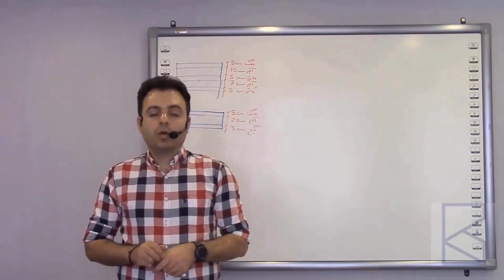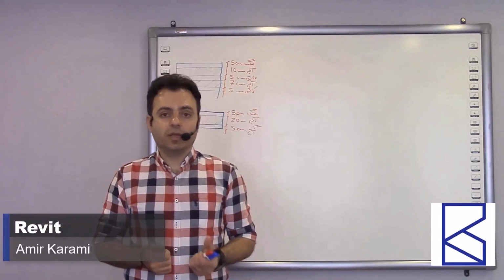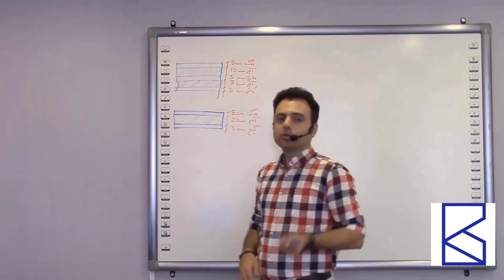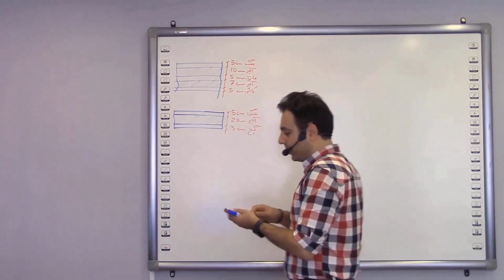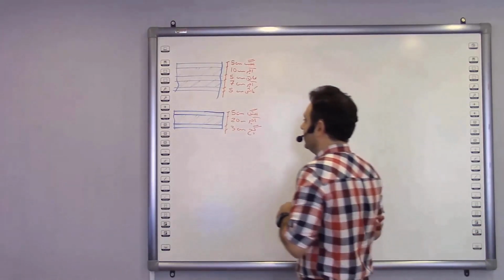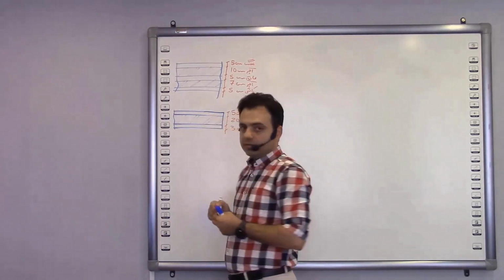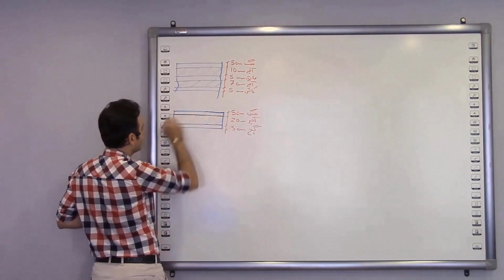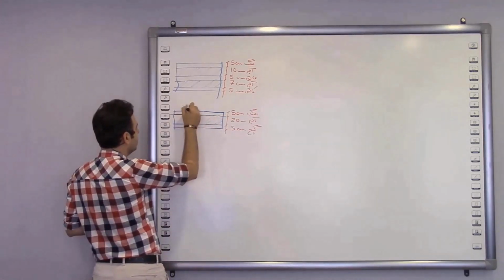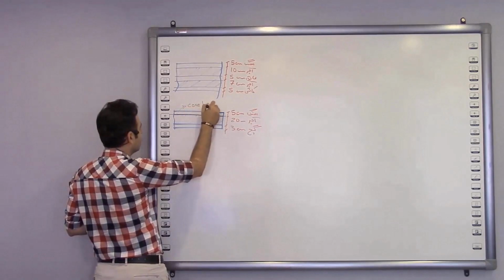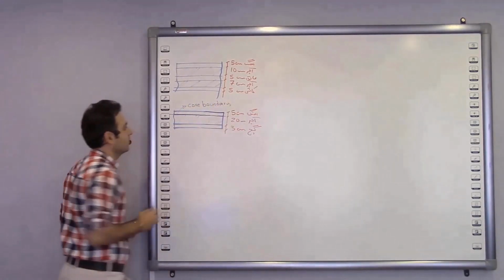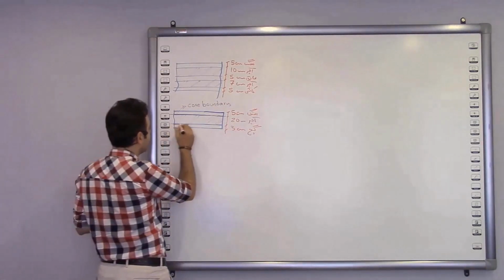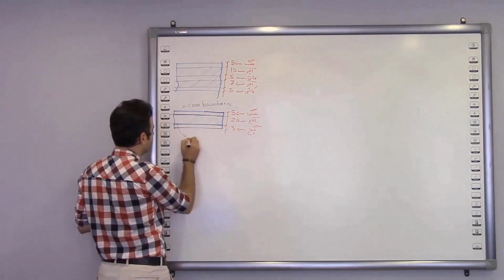Alright, now let's go for the walls with multiple layers. Imagine that we want to define this wall and you need to know only one more point to do it. We have a boundary between finish and the structure of the walls. See, this is the boundary. Now, we call this boundary in here the core boundary, a boundary between the finish and the structure of the wall. And also know that it's on both sides, so we have it here too.